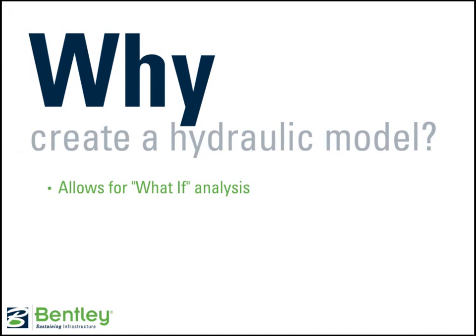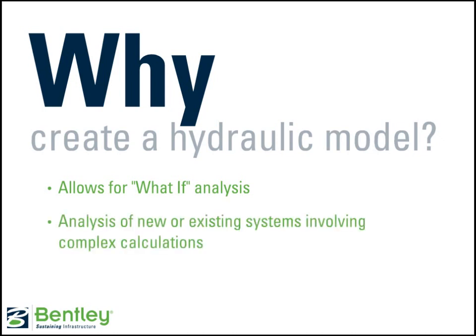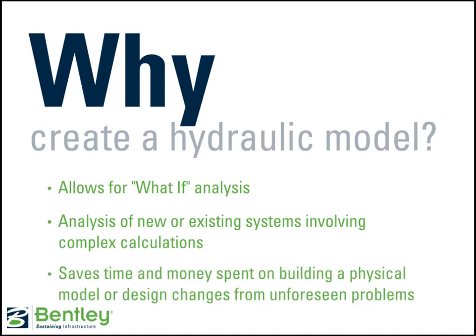Your chapter may consider why you would want to create a hydraulic model. The model allows for what-if analysis. It is useful for both designing new systems and analyzing the performance of existing systems through complex calculations that aren't easily done by hand. With the model of your real-life scenario, you can determine what is going on inside of your system. You can test proposed alternatives in the model without having to build a physical version. For a water network, it enables you to evaluate the distribution of pressures and flows inside the network. The design could be tested with a new pipe material or a different size pump, for example.